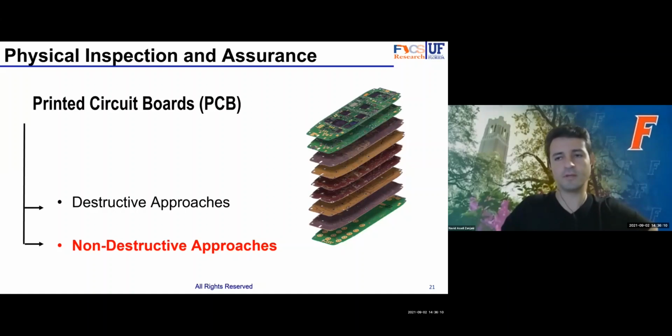A few new, by new, I mean maybe the past 5-10 years, we have quite a few techniques specifically for flat panel samples like PCBs, like laminography, where you try to move around the board in a way that you get around the noise or this attenuation that happens when a feature is under the shadow of a high Z sample, like a capacitor, that can create that noise. Okay, but still there is a lot more to be done there.